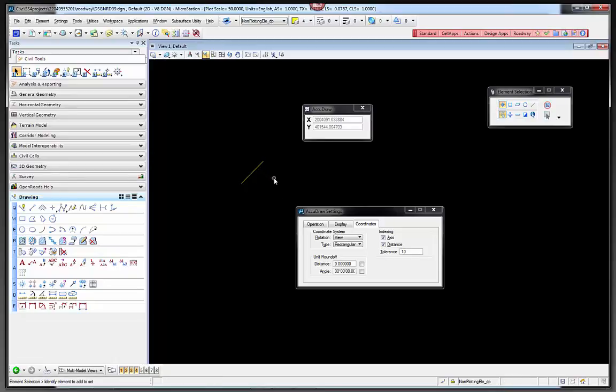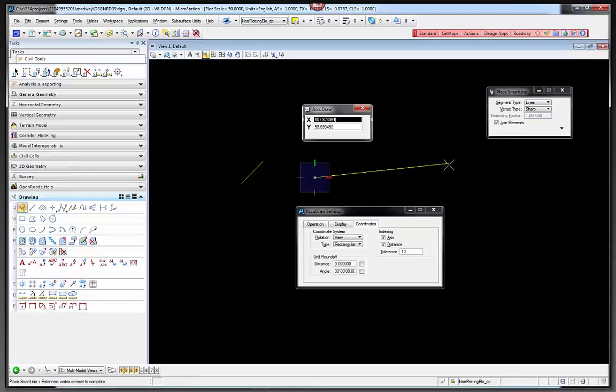It could be used for view settings also. If you start a line and want to lock it in the X, you can key in an X key, which is a shortcut, and that locks that distance. Then if you want to lock the Y, you can lock the Y like that, and then you draw the line that way. And you can do that within side views, top views, that type of thing.